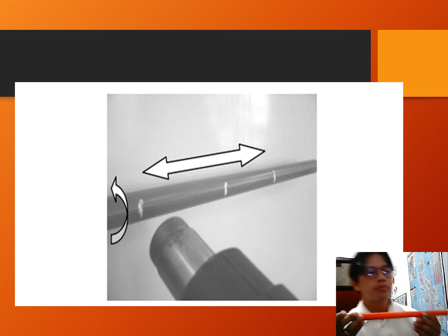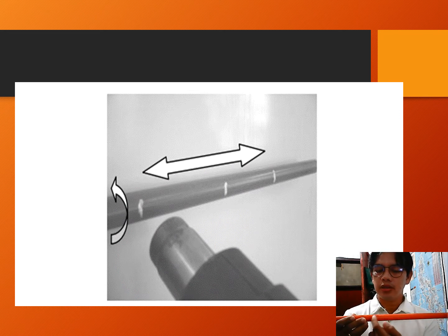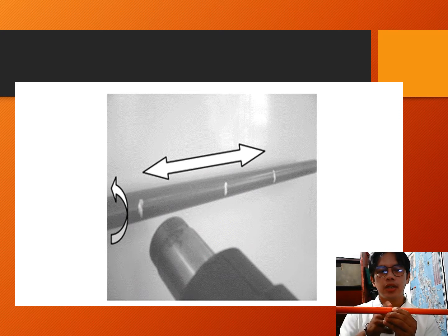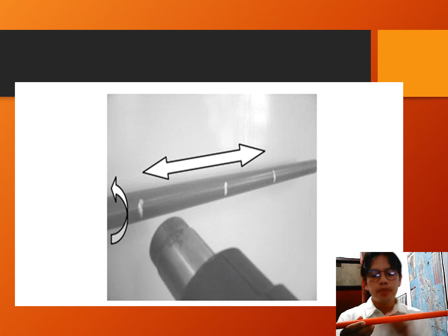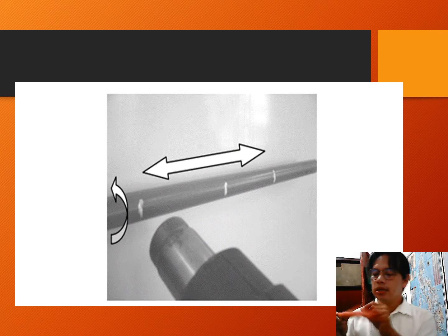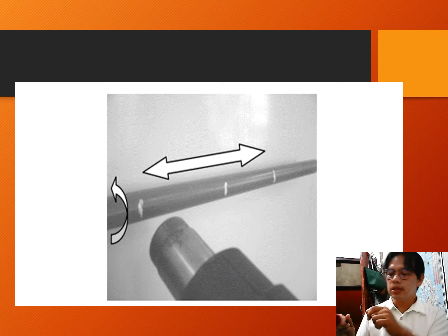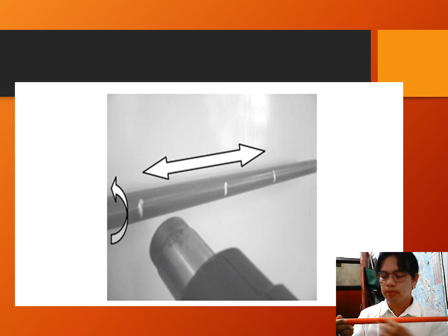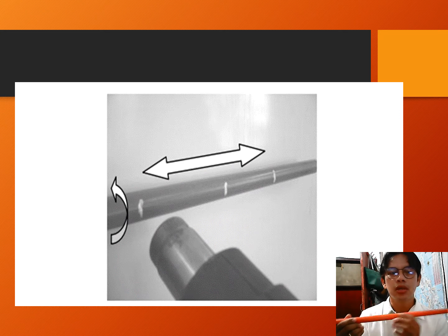If this is the PVC, from the edge you have to measure 300 millimeters. From the 300 millimeters, measure 1 inch to the left and 1 inch to the right. This would be the focus of your heat gun to have the perfect 90 degrees angle bend.